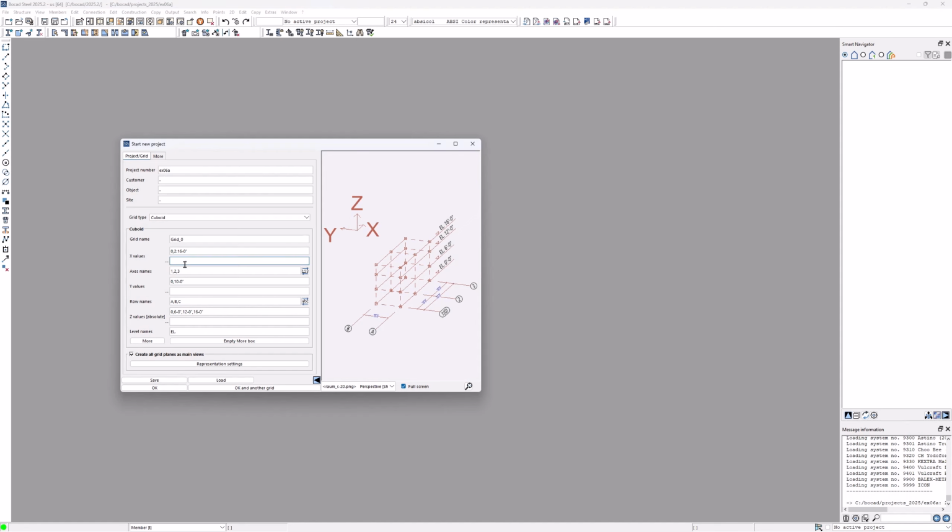And we'll start again with the grid. So we'll have 20.5 feet. Axis 1 will be sufficient. Then we have 16 feet 4, comma, twice 20.5 feet, comma, 16 feet 4. Enter, and the preview will update.